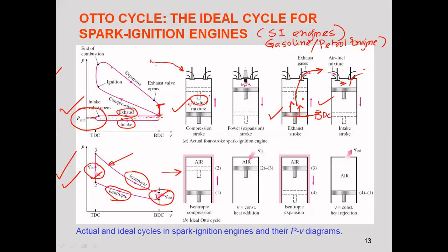The piston movement tries to compress the gas, but the open valve will try to neutralize or normalize the extra pressure by exhausting or exhaling the extra gas. Therefore the pressure will remain constant. That is the idea behind this constant pressure intake and constant pressure exhaust.